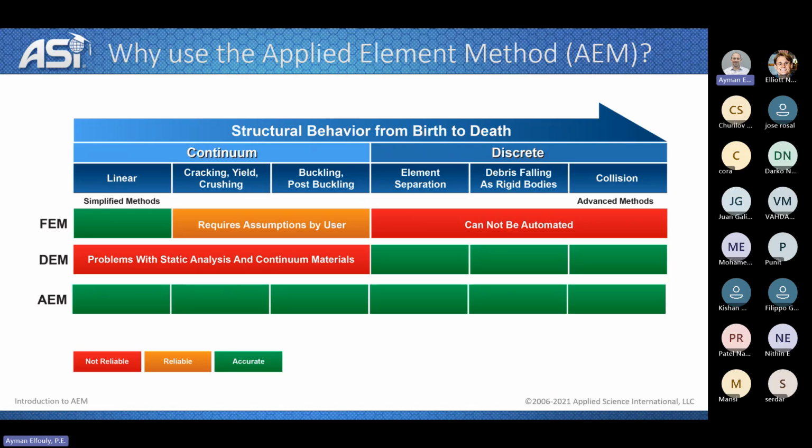Then it goes to the discrete phase where elements start to separate from each other, leading to debris, and this debris falls and collides with each other or collides with the ground. Finite element analysis is a very good numerical method for linear elastic analysis. If you go into more details like more behavior in cracking, yielding, and crushing, and so on, you have to